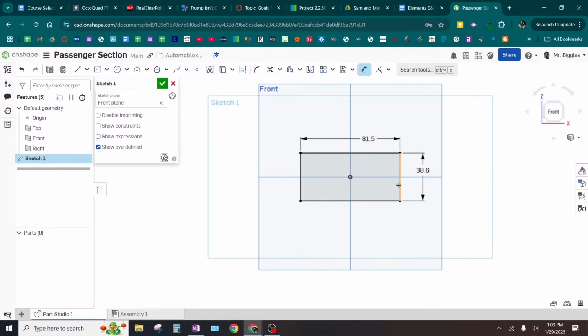Now, for me personally, I would round the corners in the sketch because it's an extrusion. So I want to get this profile correct, and then I'm going to extrude it. So I'm going to round the corners. We don't really have a great tool for measuring this, but we're going to assume that these are parts of circles. If you look at them, they may appear almost more like part of an oval, but we're just going to assume they're parts of circles.